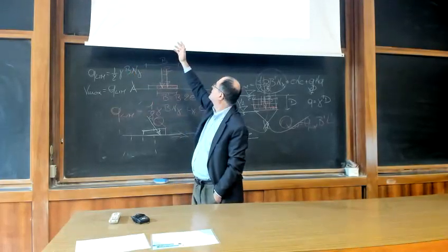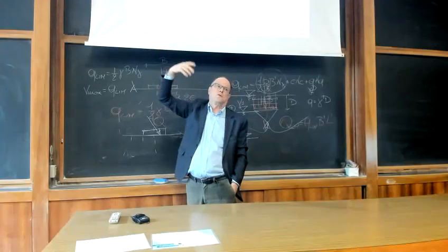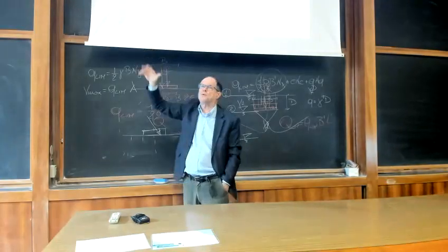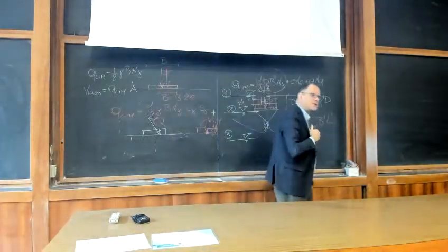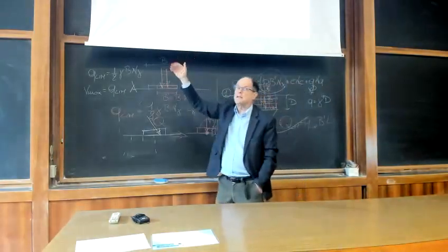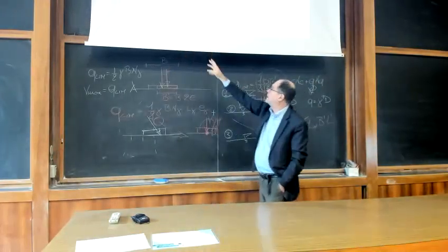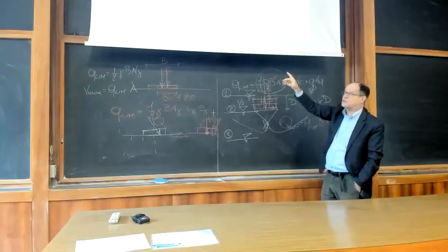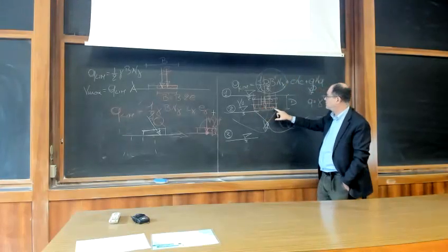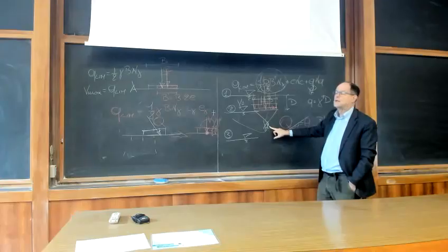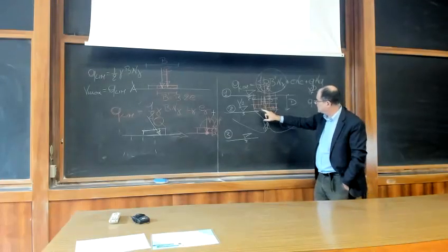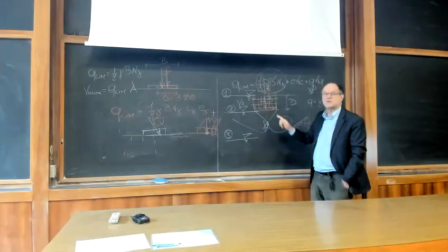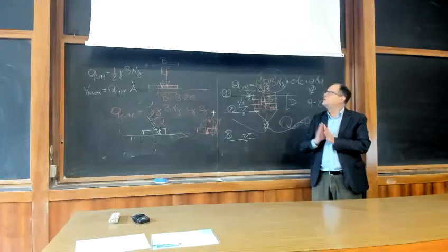So it means that the arc tangent of that expression is greater than 45, let's say 50 degrees. So you have an angle of the initial tangent which is 50 or 55, I don't know, whatever it is. But this is not possible, and it is not conservative, because remember, when you are at a very low vertical load, you have a sliding mechanism, and that tangent should not be greater than the friction between the footing and the soil. And that friction delta between this and this can be, say, around 30, 35, depends on the soil, on the roughness of your footing, but cannot be 50.